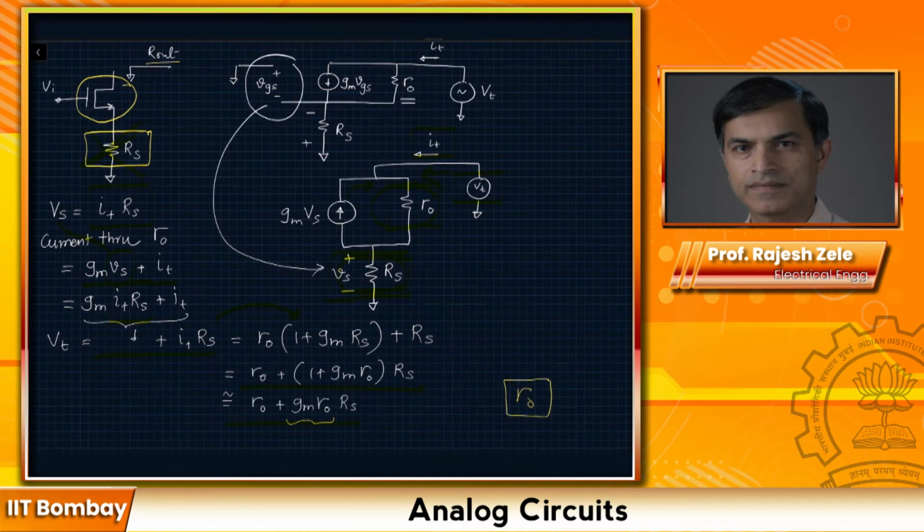What is the self gain of the transistor? It is Gm Rout. So here we can see the resistance looking down is the original Rout of the transistor, the output resistance of the transistor, plus Gm Rout times Rs. So the key insight here is, again, by doing source degeneration, we are able to increase the output resistance of this stage of the transistor. We use this trick quite a lot when we want to have higher output resistance, to boost the output resistance.